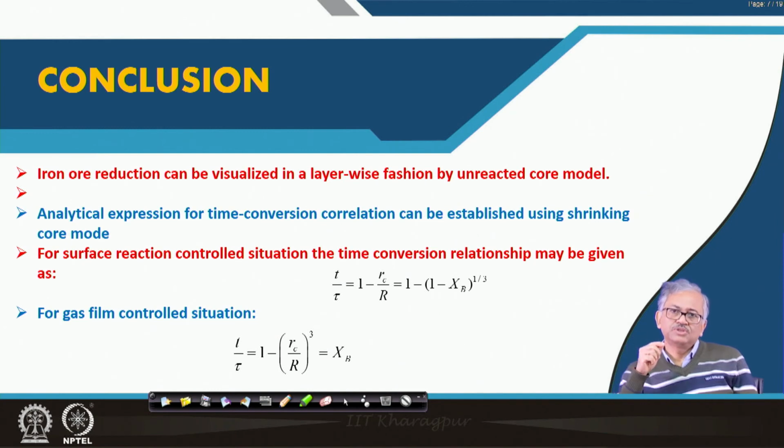And subsequent layer formation can be done by iron ion diffusion through the oxide layer to the magnetite-oxide interface, and then it can reduce the Fe3O4 to FeO, that is the oxide. Then iron again can diffuse through the magnetite layer and reach the magnetite-hematite interface and reduce the hematite to magnetite.